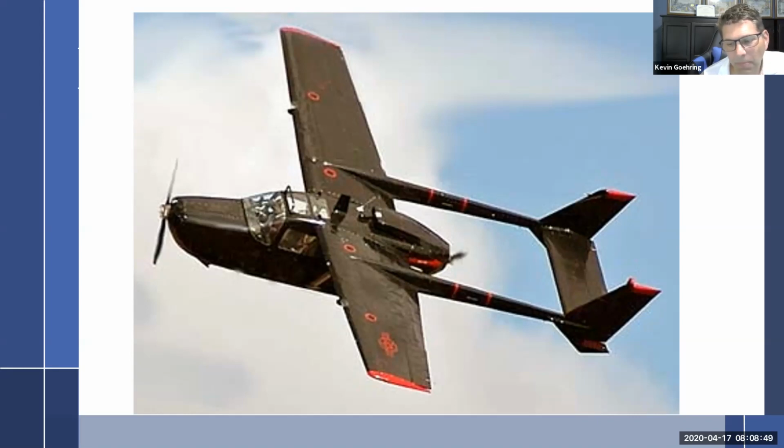So what would happen, people would take off. And remember, you can't see the rear engine. And once you've taken off, you really can't hear it because you can hear the front engine. You just know you have this engine noise. And they weren't looking at their gauges, and you can't feel it because it's inline thrust. If you had a twin on the wings, you would feel one engine pulling you one way or the other if it wasn't working. So this one, you can't feel it. So pilots were taking off, and it didn't climb worth a dang on one engine. It almost didn't climb. Some people say, you know, you lose an engine on it, the front one takes you all the way to the crash site.